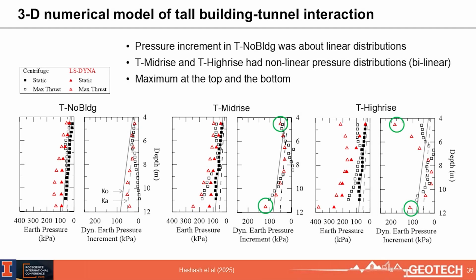So there were lots of simulations we had to do ahead of time to ensure safety, yet the viability of the results. And then we started looking at, we were focused mostly on the response of underground structure, what kind of earth pressures we were getting there. And you might have heard of something called Mononobe Okabe earth pressures. And in some places we found that we have less, and in some cases more. It all depended on the exact configuration of the tall building and the underground structure itself.